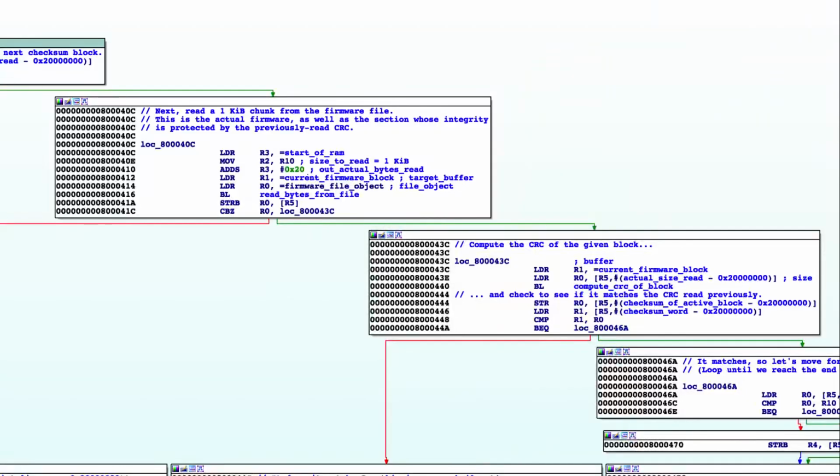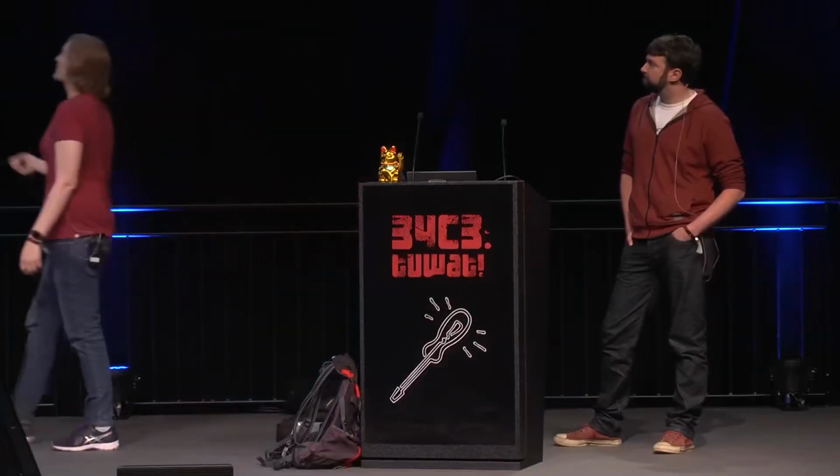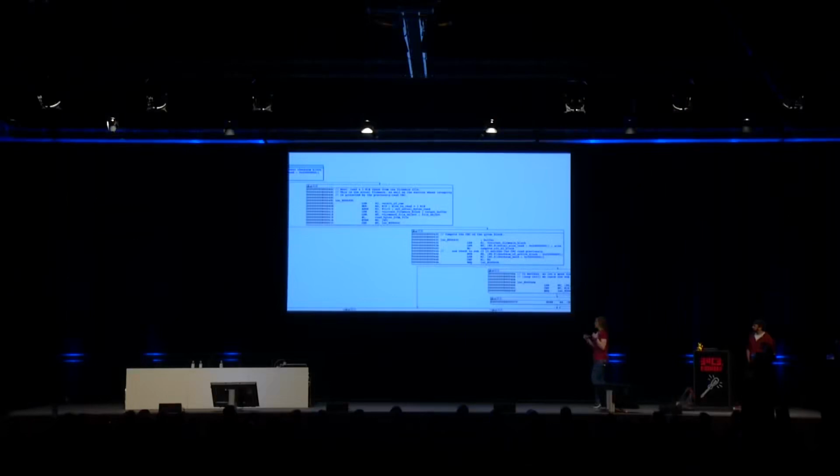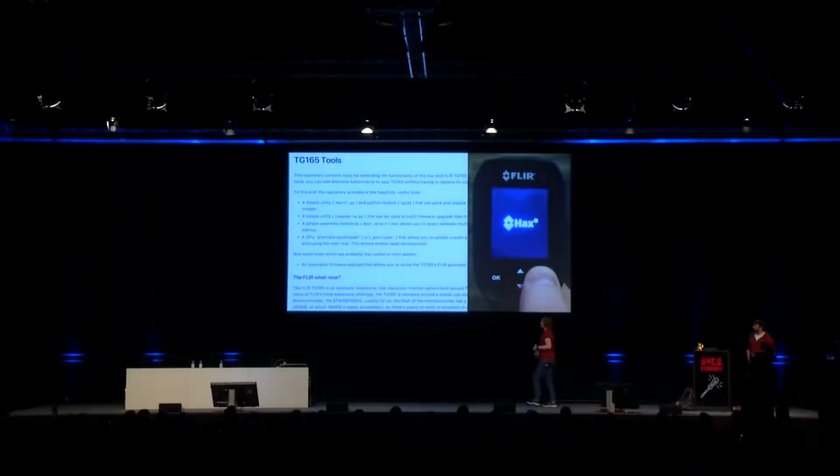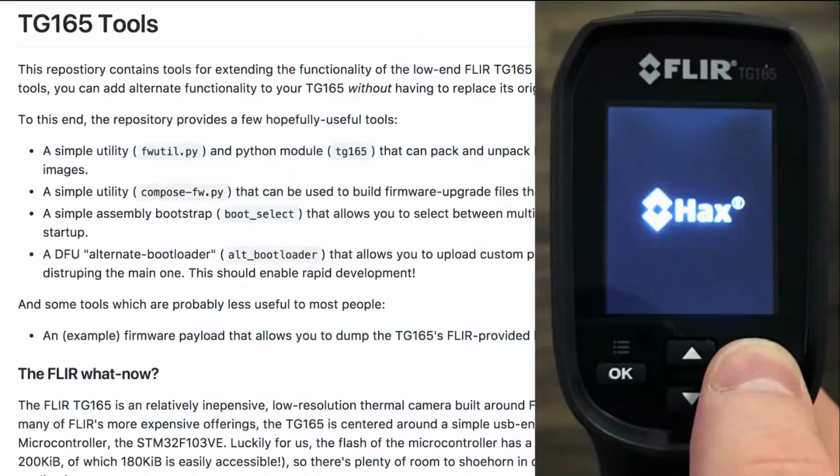Right, the bootloader itself that's on there, that's not contained in those firmware update images, it knows what is used to actually talk to it and to upload things onto there. And so if you're able to get that bootloader out somehow, then you can easily go reverse engineer the code and figure out what the actual structure of that metadata is. And though I didn't actually get the bootloader out by glitching, eventually I figured out the format, was able to find another vulnerability and then get the bootloader out via some simpler exploits. This device was able to be hacked and there are tools for it. And it would have been a lot easier to do that if we had the ability to get the bootloader out almost immediately.